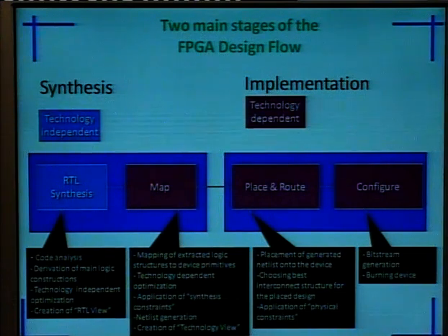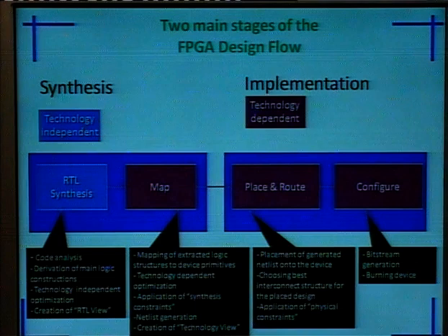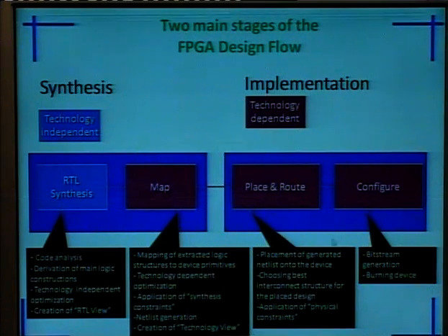So in summary, in this lecture we discussed first the basic VLSI design flow, then basic concepts of VHDL, then combinational circuits implemented with the help of VHDL coding, and then those VHDL codes were simulated and synthesized, and the synthesized design is ready for implementation on FPGA with the different steps of placement and routing. In this way, we can design our combinational circuit model from specification to the end product.